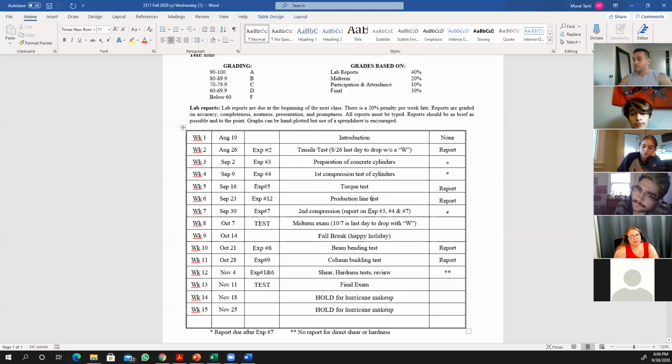All you do is you take samples from the same spool. We have aluminum, copper, and steel wire samples. Each student takes samples from each spool, and then you test each wire under tensile and measure the failure load when it fails.